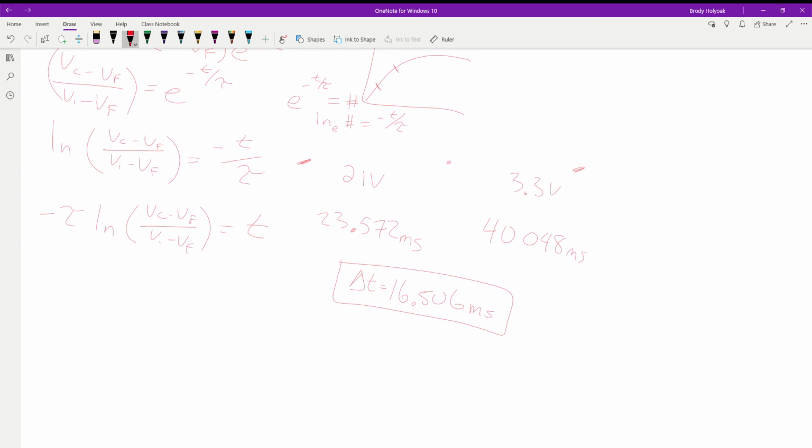Or we have it delay. We have it watch the voltage. Once the voltage comes up to 2.1, we want it to wait 16.5 milliseconds at least before it samples again, which we can do. We can program things to do that. We can program these to get these samples anytime that we need it when we're building these things. This is getting into some technical stuff, third, fourth, fifth semester, but just so you guys know, this is why we do this.